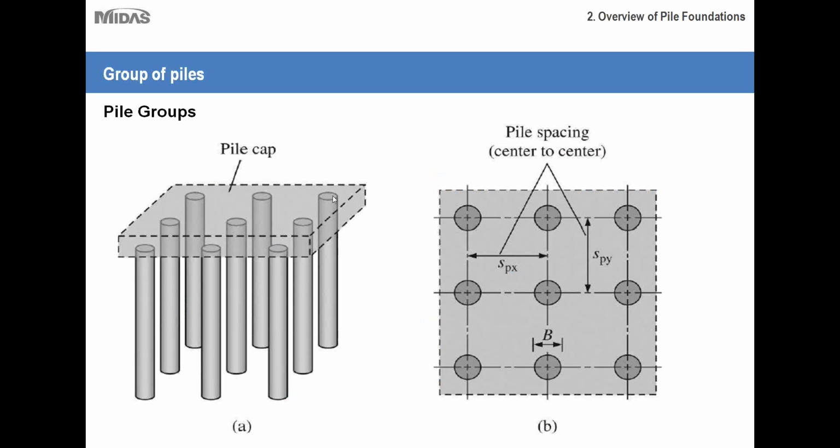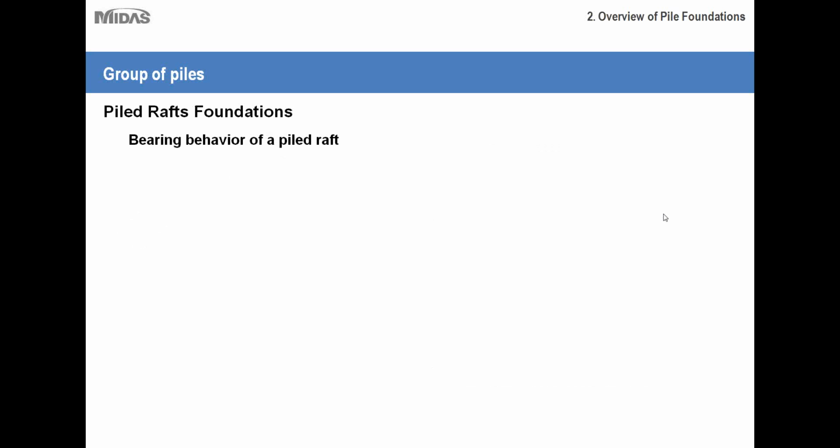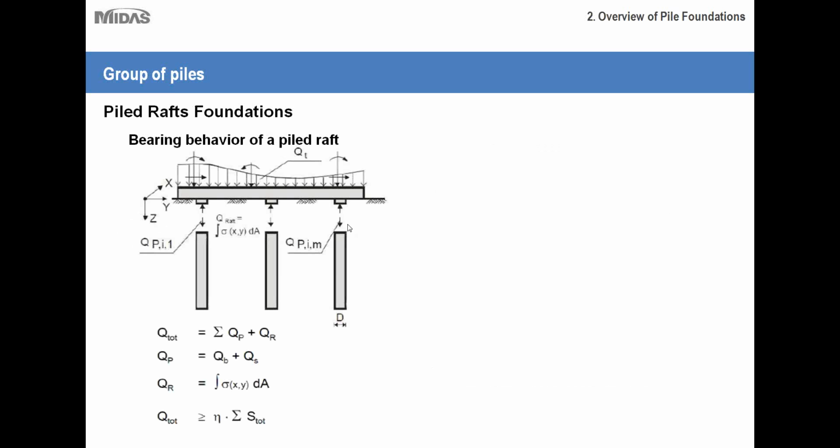As far as pile groups, as you can see, if you have a group of piles, there's a pile cap put into place here, and a lot of the design work goes into deciding the spacing of your piles as well as the size of the piles themselves. Now let's talk about pile raft foundation.